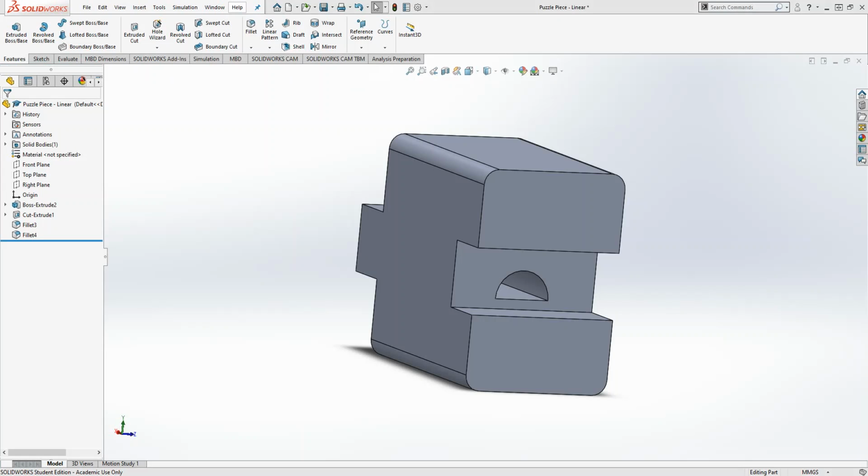For now, we're just going to stick with up to surface, and we just want to cut through the surface entirely. So I've selected my original sketch, the contour is what they call it, and then I selected a new face to extrude to.